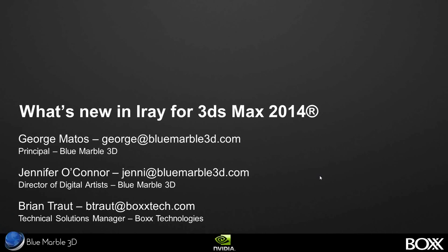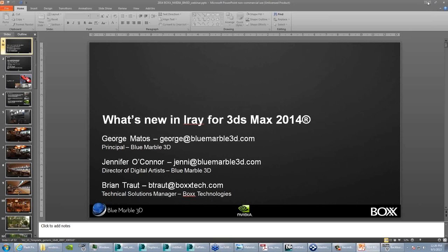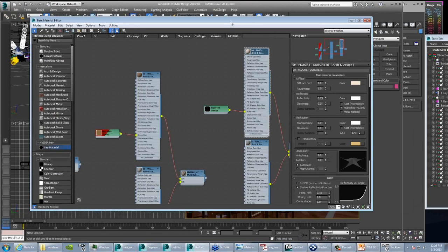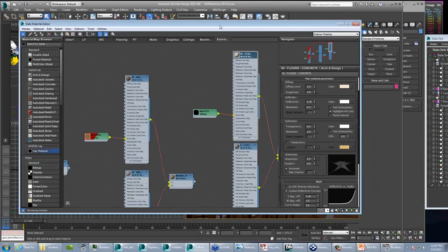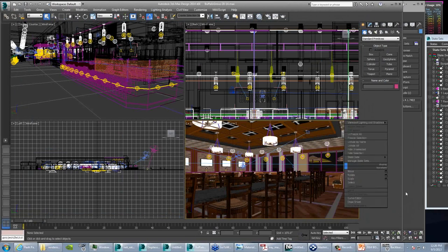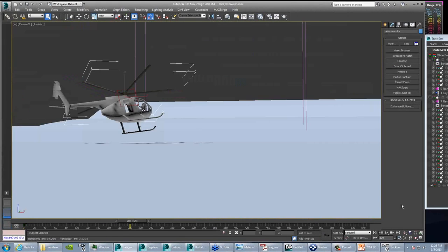Your memory use value in the render process window, after it has determined scenes fit into a video card memory. Which setting? Memory use value in the render progress window, after you click render and it's chugging away.